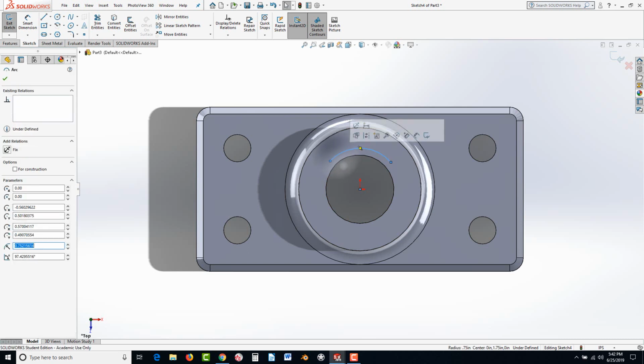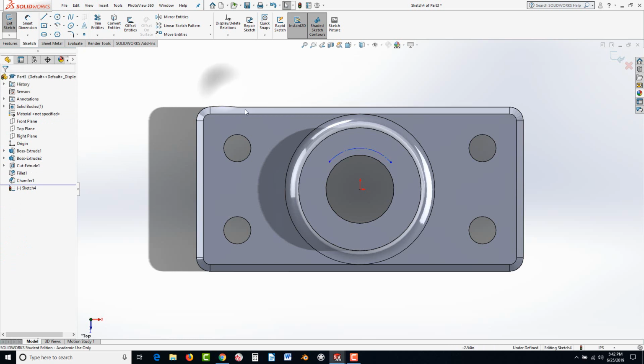And now click on that arc, and you'll see an option for construction geometry. Turn it to construction geometry. There's also a construction geometry checkbox here. Either one, as long as something's selected, you could always convert it to construction. That means it's not going to cut that, but it allows us for construction entities. I mean, we could use it actually, in this case, to align our text to it.